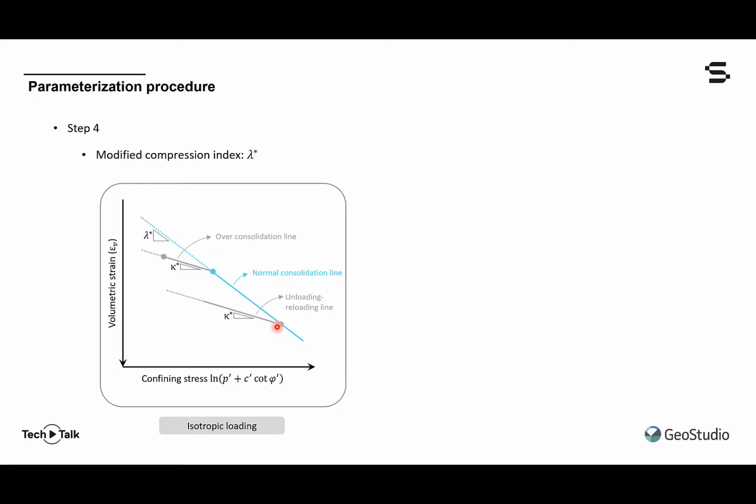In other words, if we had taken that previous example that I just walked through, let's say that the specimen was isotropically compressed along the overconsolidation line, and then it yields in isotropic compression, and we track along the normal compression line. Hence, it is often referred to as the isotropic normal compression line and designated ISO-NCL. But anyways, if we did that, we tracked down this line and then we unloaded, we would be on the unloading-reloading line.